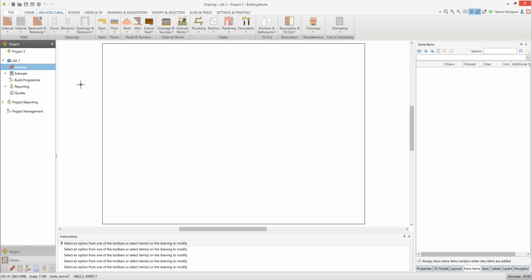I'll talk about using the delete key to delete items and the escape key to finish doing an action. I'll also show you how to repeat the last action by middle clicking. Master these key skills and you'll soon be drafting your own designs in minutes. Let's start by recapping how to use the Shift key to draw walls at right angles.